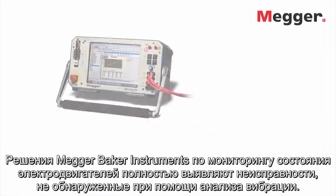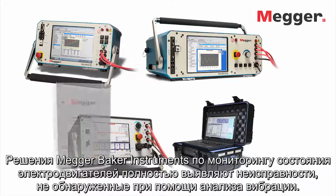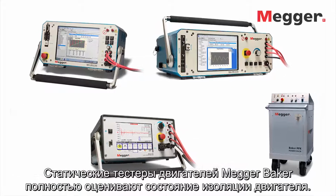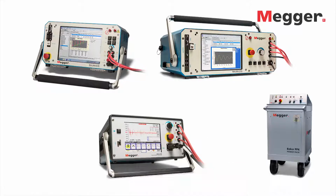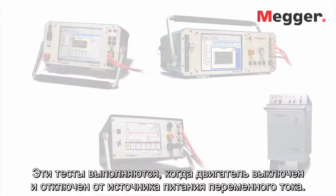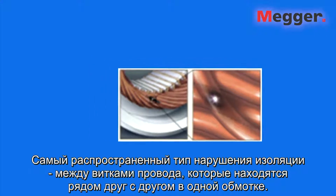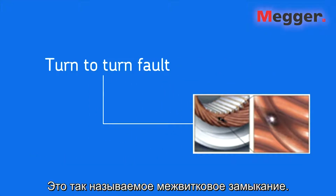Megger Baker Instruments electric motor condition monitoring solutions completely address the faults not covered by vibration monitoring. Baker static motor testers completely assess the insulation system of the motor. These tests are run when the motor is off, disconnected from the AC power source. The most common insulation failure is between turns of wire that are next to each other in the same coil. This is called a turn-to-turn fault.